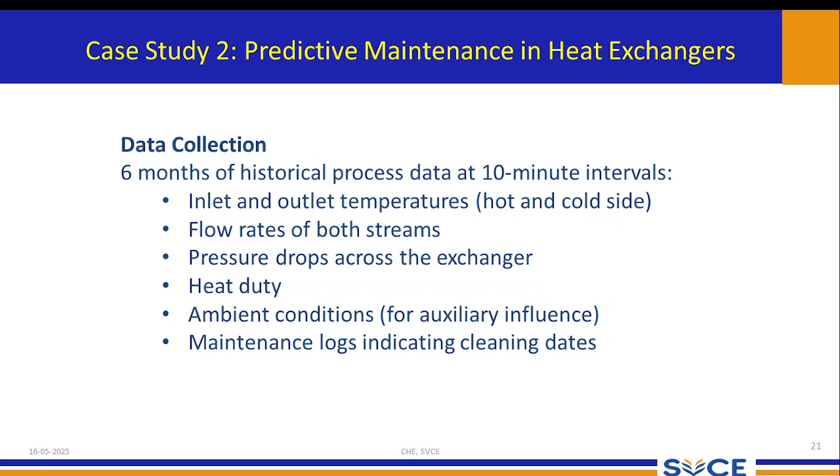Similarly, for the heat exchanger, what are the factors that need to be recorded? What is the inlet fluid temperature? What is the outlet fluid temperature? What is the flow rate of that fluid? The pressure drop occurring on the shell side or the tube side. What is the U, the duty? What is the ambient condition? Maintaining logs indicating the cleaning days. This is the data collection that needs to be done for the heat exchanger.